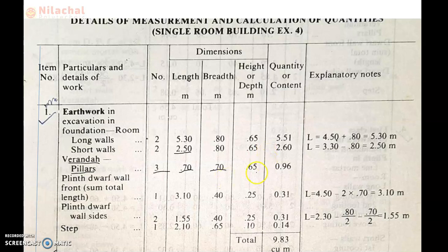So after that we go through the drop wall part. First of all we discuss the drop wall. What do we mean by drop wall? The drop wall is basically constructed in the case of a veranda. We know the veranda is an open structure. So in the case of a veranda, the wall is constructed below plinth level, from the bottom of the foundation to the plinth level. After that, above the plinth also, the veranda wall is constructed.